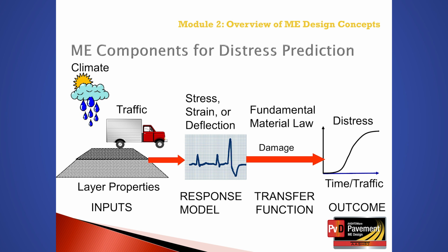The pavement response models are used to calculate critical pavement responses that vary from month to month and year to year. Examples will be included in the latter modules that illustrate the change in modulus of different layers throughout the design period. This consideration of changes in the pavement responses that impact occurrence of distress is important.